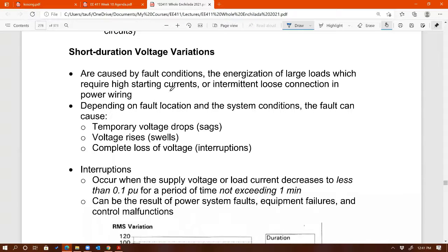You learned that in 295 lab, right? That as soon as you turn on an AC machine, an induction motor, then you're going to be dealing with significant starting current, as high as 5 to 8 times normal current, right? So if the nominal rating of the current is 5 amps, then when you start induction machine, the current can go up to about 30 amps or even more.